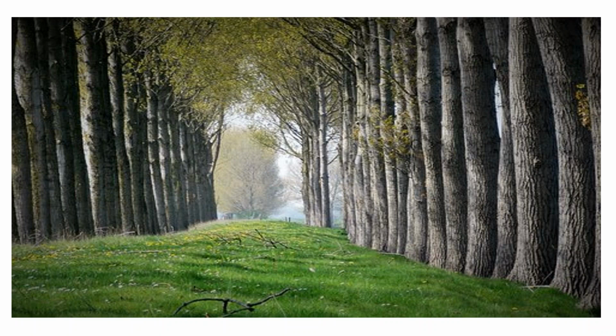So they have to keep putting more and more layers into the actual membrane to be able to stop particles. If you miss one tree layer, maybe you'll hit the second, maybe you'll hit the third, maybe you'll hit the fourth. Each subsequent layer, however, creates pressure drop. So you're actually compromising the design and the efficiency of the pressure drop decrease by adding more layers to compromise back and fix the air filtration side of things, or the removal of particles.